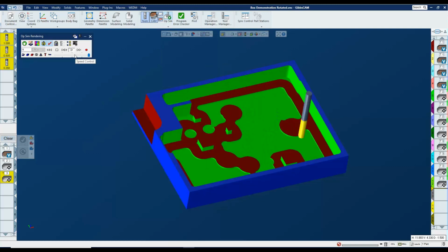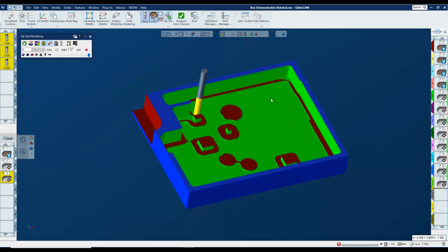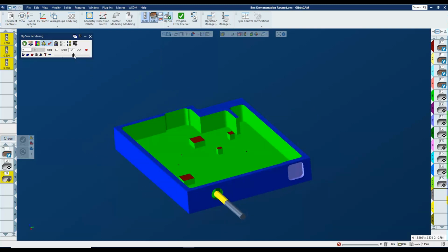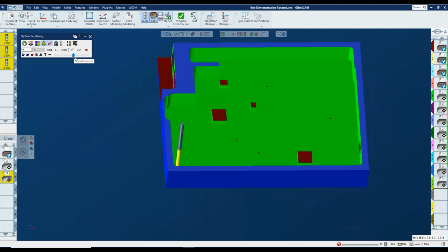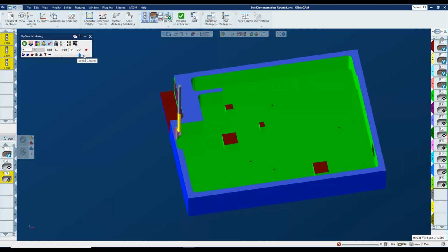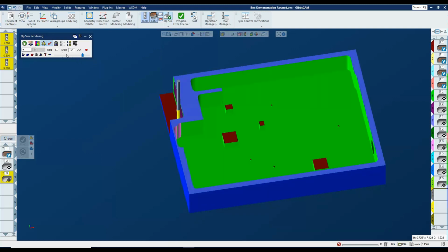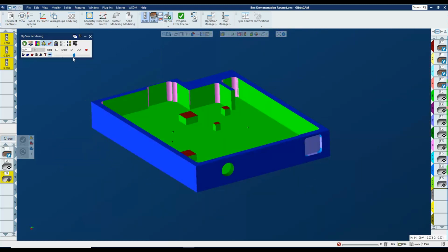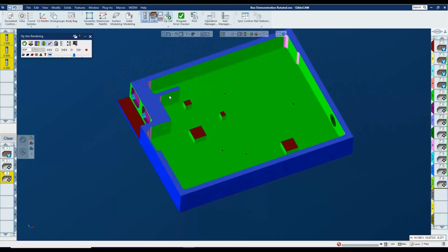So you'll notice that now we're on op 5, which is tool 2. So tool 1 was only used in the first orientation apparently. Now we can see the orientation on the other features. And now we switch to tool 3, and we'll do the first setup first, again cleaning out those corners. By the way, I can also turn on my tool holder at any time if I like. Now you can see that we're cleaning out the corners in that feature. In this feature, we didn't need to do anything with the circular feature.